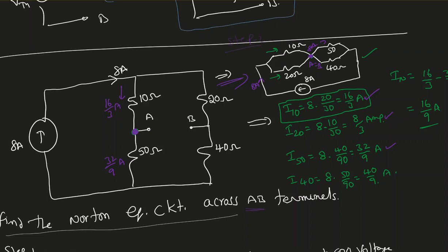In Thevenin theorem, step 1, we always remove the element where we need to find the current or voltage. We'll remove that element and label the terminals, right? That is our step 1. Here also the same. So remove the element. Instead of opening it, here what we're going to do is short circuit it. That is the difference between Thevenin theorem and Norton theorem. So here I'm going to short circuit it. I'm going to find the I Norton current.